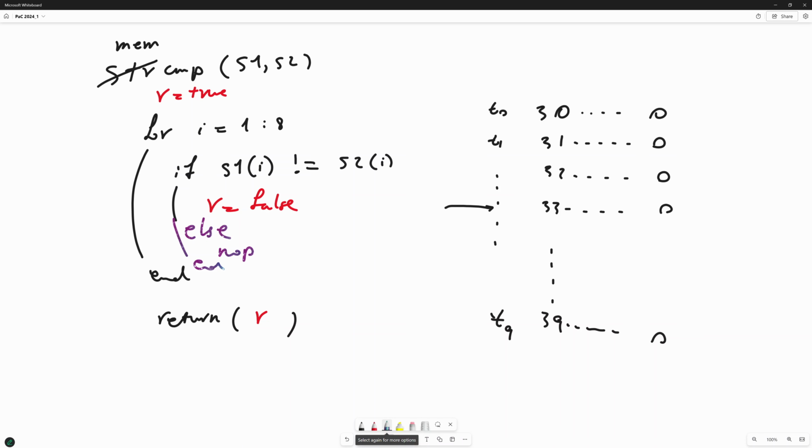If you implement something wrongly, as we will learn later, timing attacks are possible. These are attacks that look at the number of clock cycles it takes for a cryptographic primitive, or cryptographic algorithm, to be executed. If this depends on the data, on the secret, or on the input that you give, it opens the door to perform an attack to recover the key.